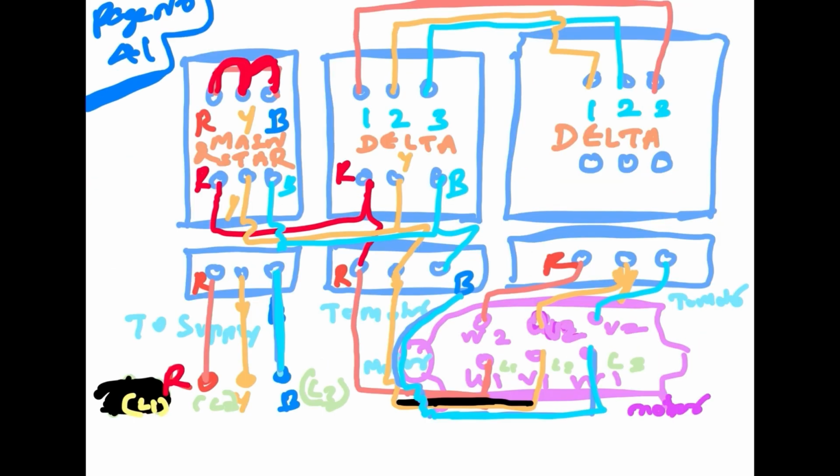The circuit diagram is shown in the figure. The first contactor is used as the main and star contactor. The second contactor is the delta 1 contactor. The third contactor is the delta 2 contactor. The first contactor terminals are connected to the supply voltages, supply lines L1, L2, L3, that is R, Y and B phases. Then the first contactor is the star contactor.